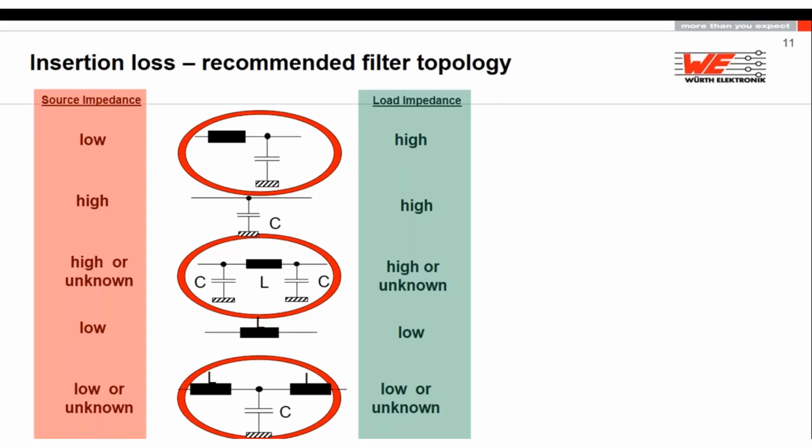With the Pi filter, I play with the capacitors. And when I see the capacitors don't have a really big impact, I go back to my LC and I try to play with two different inductors. So I have my T filter. One of those filters will have a massive insertion loss, and you will find the right solution just by trying, if you don't know exactly the system impedances, which is mostly the problem. It's not like in a university where everything is 50 ohm. In real life, you will find out that the system impedance is very, very rarely 50 ohm.